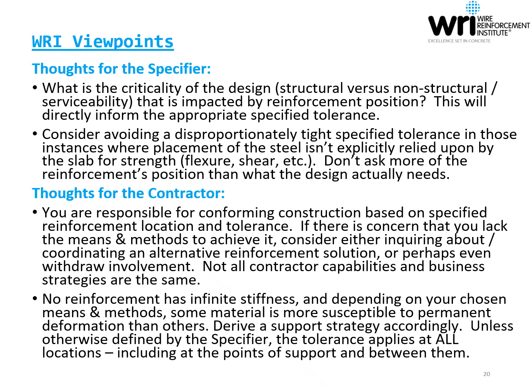And then for the contractor, you are responsible for conforming construction based on specified reinforcement location and tolerance. If there is a concern that you lack the means and methods to cost effectively achieve it, consider inquiring about an alternative reinforcement solution, or perhaps even withdraw involvement if the situation can't be shown to be favorable for your operation. Not all contractor capabilities and business strategies are the same, and decisions need to be made accordingly from one